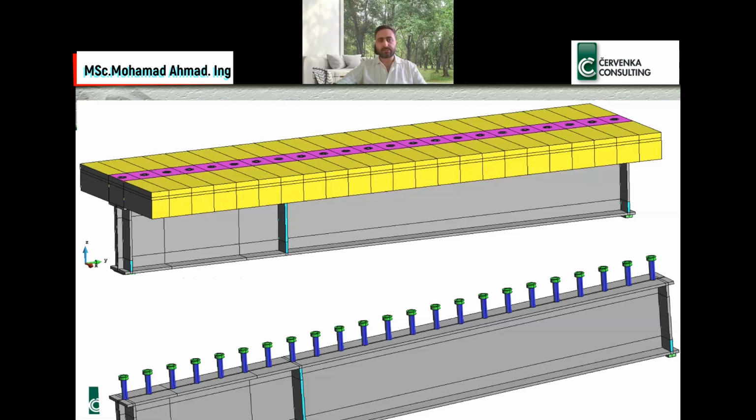You could say this is a small or a simple model, which is not true. Due to this area, where the shear connectors are inside the concrete, the model is very complicated, because you need to have holes inside the concrete or inside these volumes and connect each surface from the connectors with the concrete by interface or contact volumes.